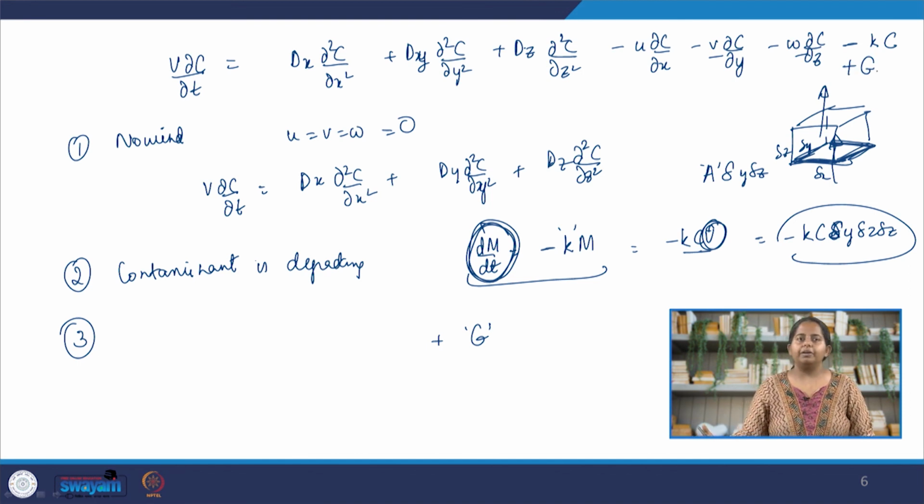Now, it might be different depending upon what the other sources are. If we have simple multiple chimneys that are emitting, we can sum up their plumes. So, we can use computational abilities here. We can say, all right, one chimney, the plume looks like this; second chimney at this location is also releasing at this emission rate, so its plume looks like this, and then we can allow the plumes to overlap and add up. This generation is different. This is not coming from a point source, another chimney which is undergoing Gaussian plume too, so we do not add it, we have to include it here. It could be per area, or it could be some other sources that are releasing the gas.